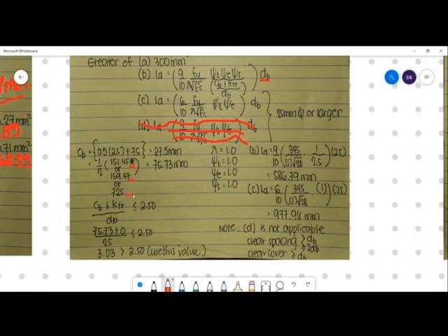So we have short direction, and we have two formulas for long direction: the center band and the remaining part. So the smallest is 151.45, so we use 75.73 millimeter. Compute C sub B plus KTR over D sub B, less than or equal to 2.5. 75.73 plus 0 over 25 is 3.03, which is greater than 2.5. So we use 2.5 as our value.